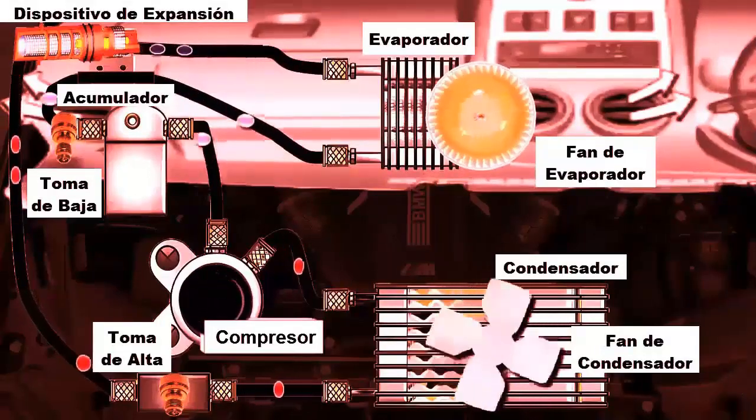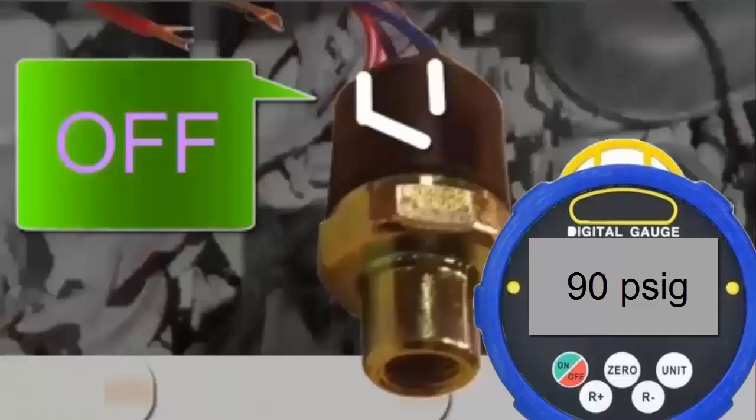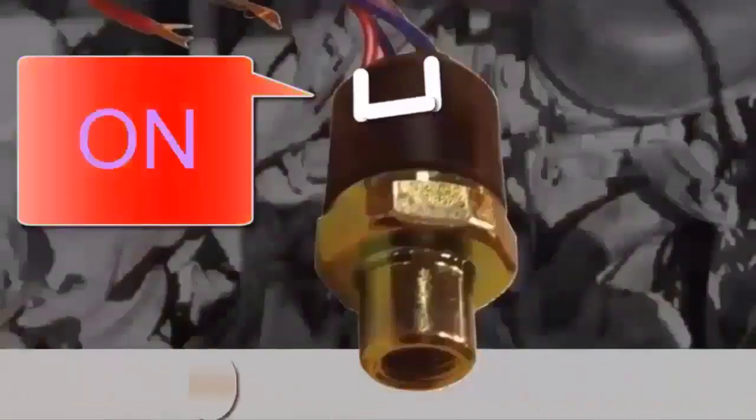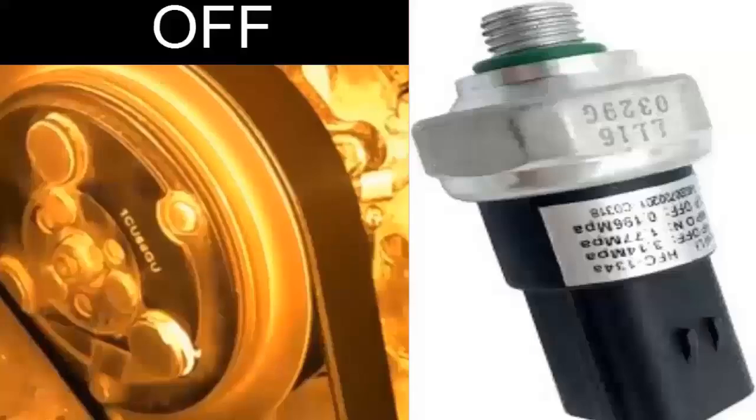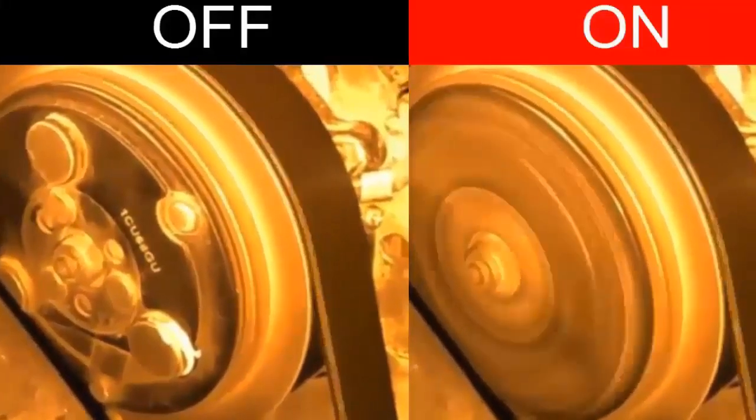Signs of a faulty low-pressure switch. A. The compressor does not activate, even when the system should be operational. B. Intermittent compressor operation without an apparent cause. C. A defective low-pressure switch may send incorrect signals, causing the compressor to stop unnecessarily or fail to shut off when required.